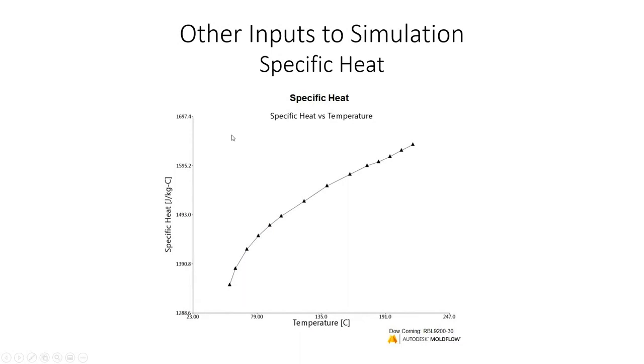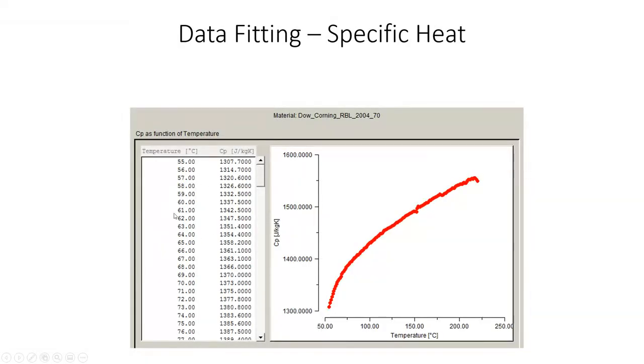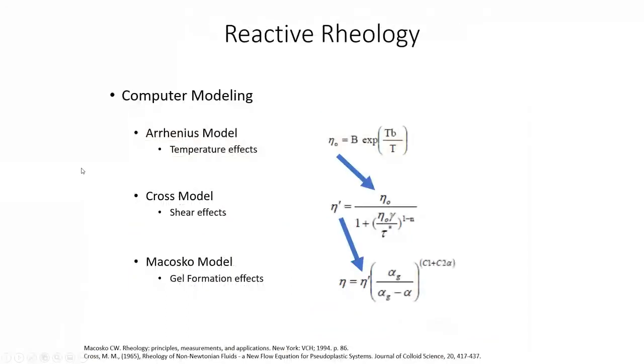And then I said it's very important to have specific heat of materials because polymers are compressible. Their specific heats change with temperature and time and pressure. And so we usually run multiple pressure specific heats and multiple temperatures, and we can relate those. And again, we have to input that into the software like I'm showing here. And so all those data points are input. And so these algorithms are soaking up all of these data points and kicking out these material characterization standard numbers.